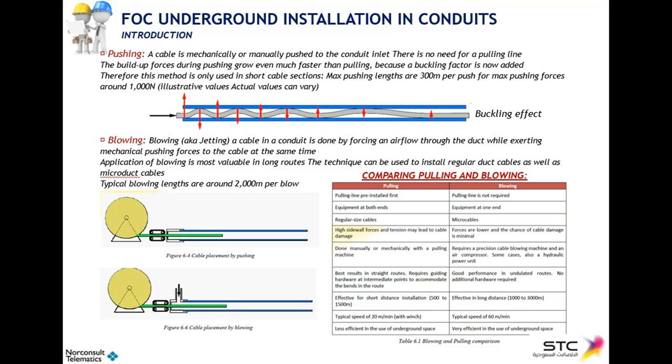You have to keep in mind that pushing a cable inside a duct has a very short installation span, and you have to be aware of why this happens. This happens because of the buckling effect.